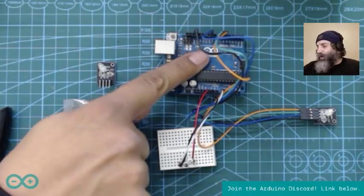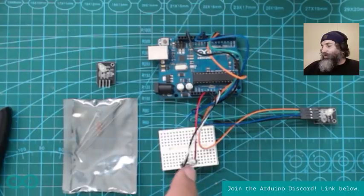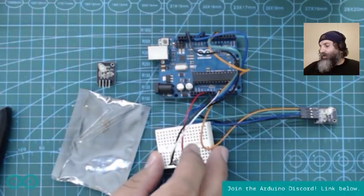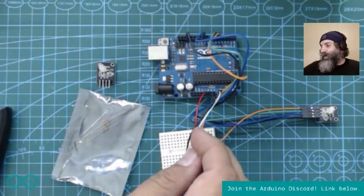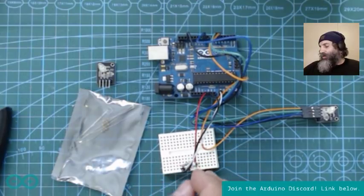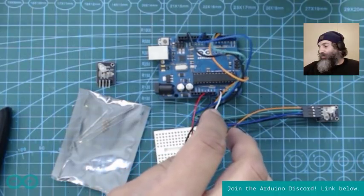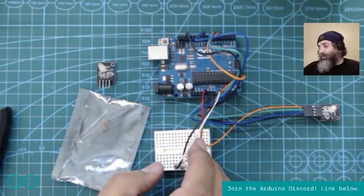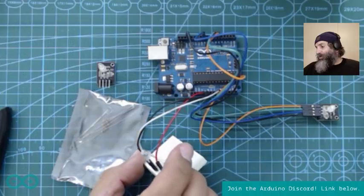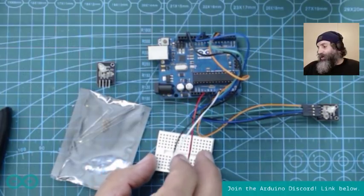So here we have the Arduino Uno board that I have to program, the breadboard with the photodiode that is connected in series with the resistor. As you see, the white cable is the one that's carrying the signal back to the Arduino board, and on the other hand, there is 5 volts that are connected to one of the pins of the diode, and the ground that is connected to the other pin of the resistor.